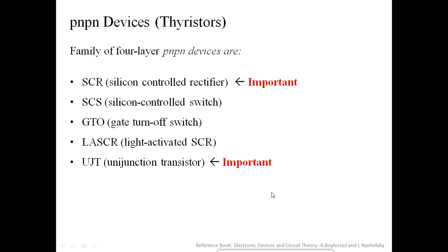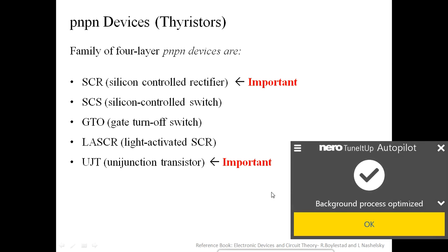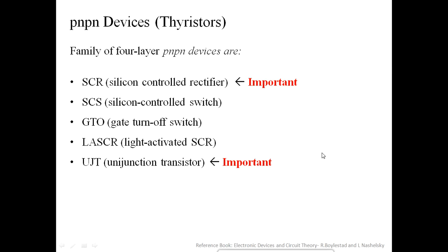The main difference between a normal rectifier and a silicon controlled rectifier is that a normal rectifier doesn't have any control terminal. You just have an anode and a cathode, whereas in the case of an SCR you have a dedicated third terminal which controls the entire operation of the rectification process. However, with respect to the characteristics, a silicon controlled rectifier has completely different characteristics, although it can be used mainly for switching purposes.